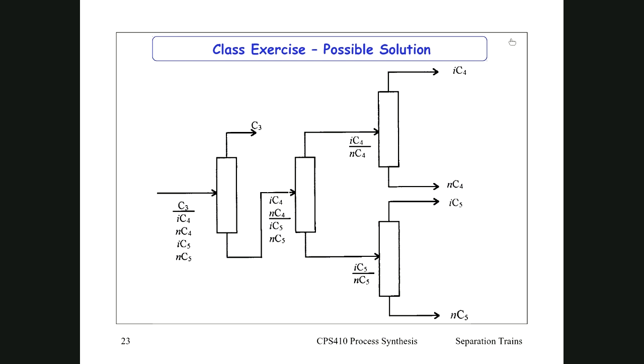Yes, Jared. So surely this almost directly contradicts heuristic 6 though, because C3 was an incredibly low flow rate, whereas you're splitting a huge amount of flow down to the bottoms product. Yeah, it does.